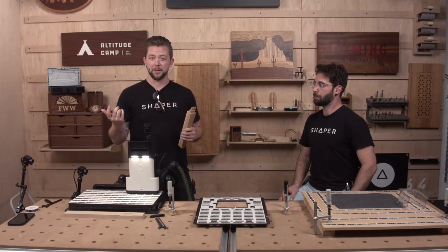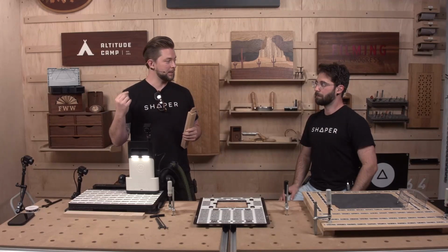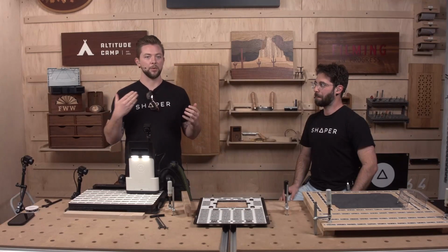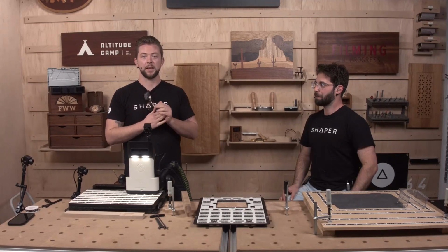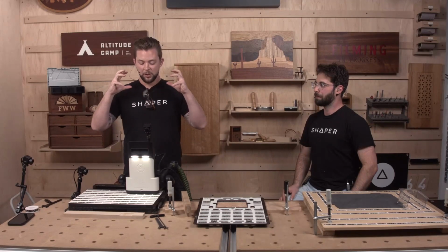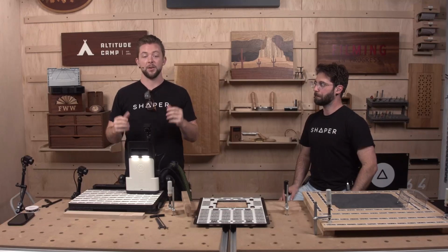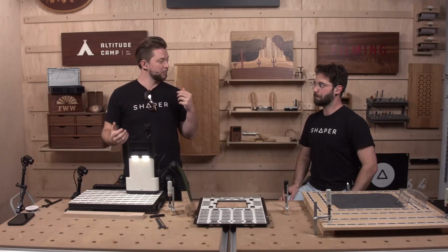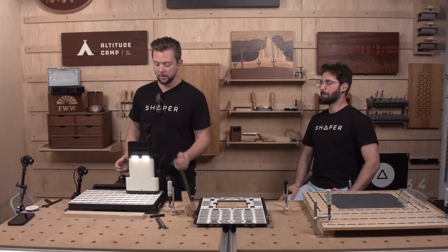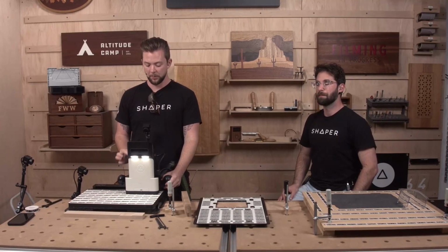The tricky thing about this has always been remembering and not messing up on your depth, because you're inputting it every time, and you want to make sure that your mortise and your tenons are going to be bang on. And if you're in production mode, you're not thinking about numbers. You're just cutting. So we want to make sure that we make that process as fluid as possible. So we're going to get you a little reminder of where you should be depth-wise.